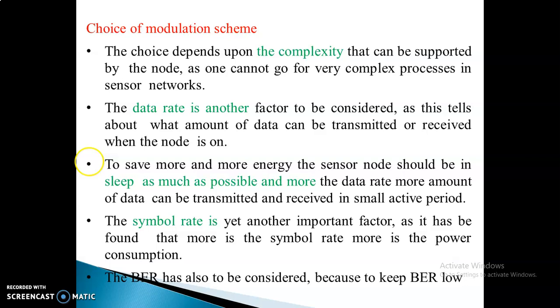The next one is about wave propagation effects and noise. Wave propagation effects are reflection, diffraction and scattering. Reflection: when a wave propagates from one medium to another at a boundary, there will be a reflection. The amount reflected or transmitted depends on the material and the frequency.